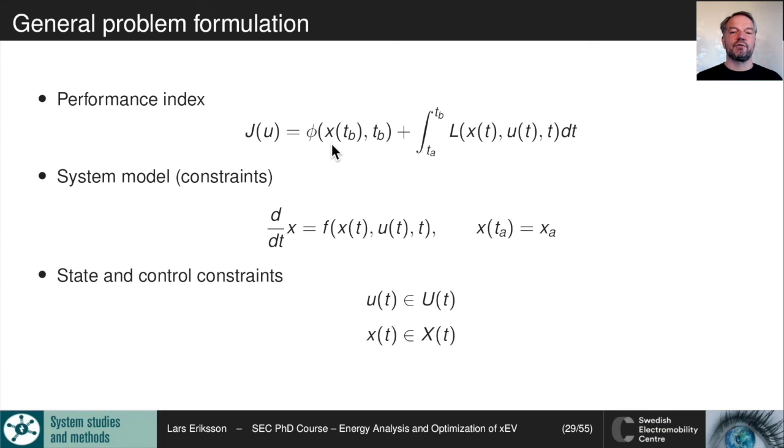And then we're enforcing it to say that deviating from the desired state of charge will cost extra in terms of fuel, because that means that we need to use the combustion engine to generate more electricity. So having a non-optimal state of charge at the end will cost fuel in the future, and this function can then keep track of such things, so you can model these kinds of effects.